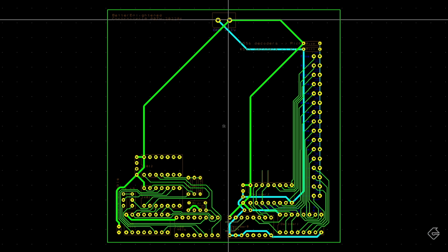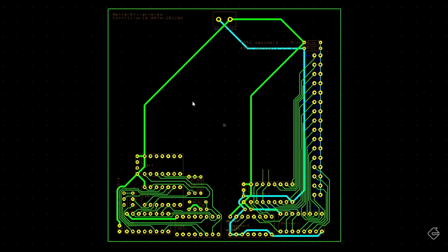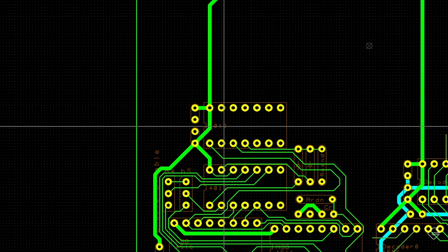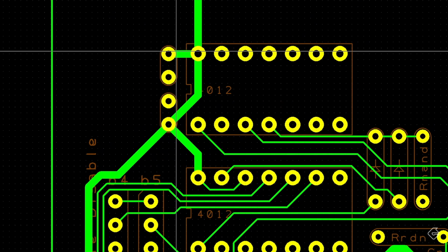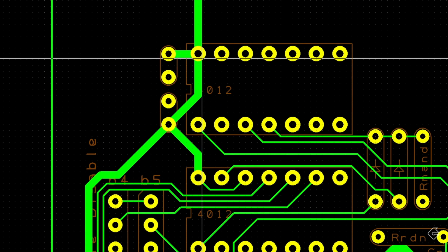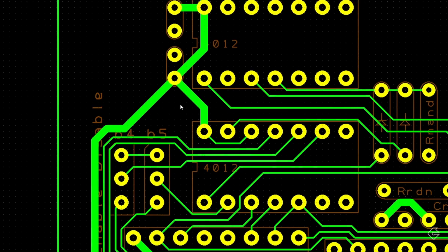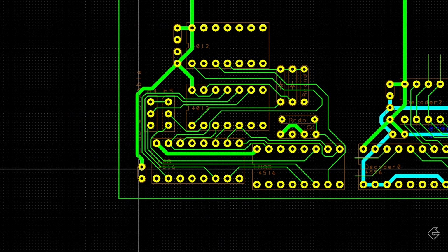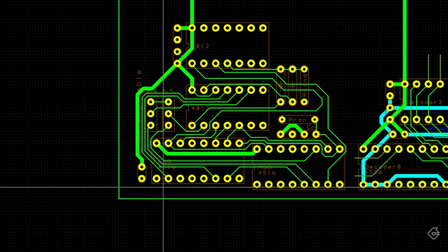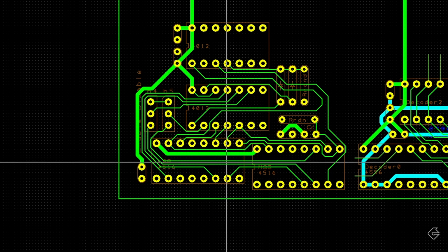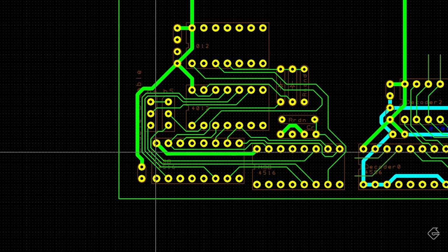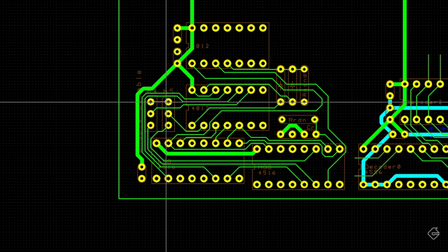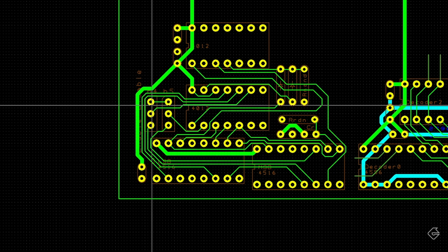So I brought plus 12 volts in from the top down into the first 4012 chip over here, and you can see how it's also connected to the bypass capacitor. It continues on to the next bypass capacitor and also connects to the 4012 chip over here, and then it goes around here, connects to this bypass capacitor, and it stops. I've connected these 2, 4516, the plus 12 over here together, but notice they're isolated and not connected. I've also connected these 2 together. These are the plus 12 pins of the jumpers together, so they're now plus 12.